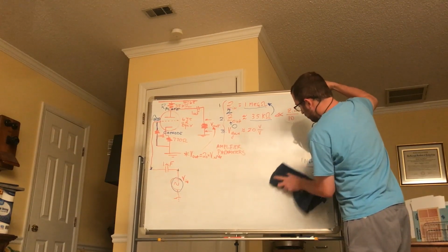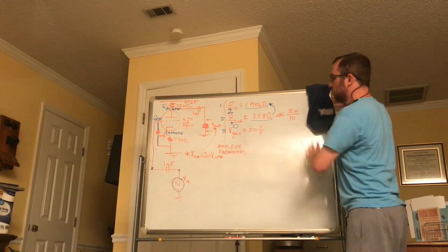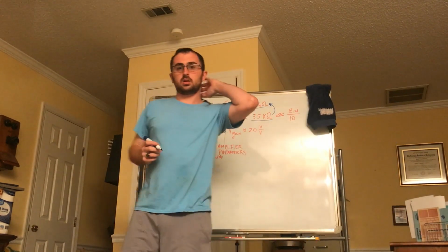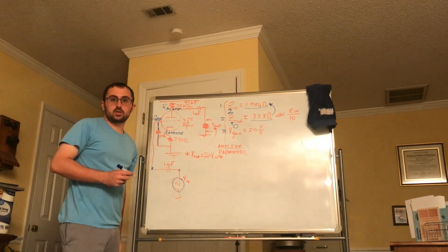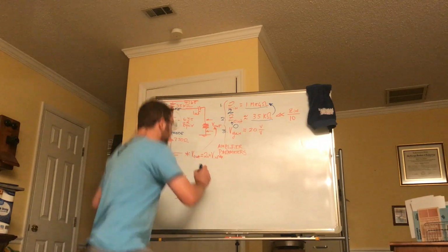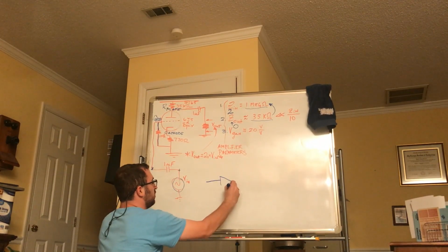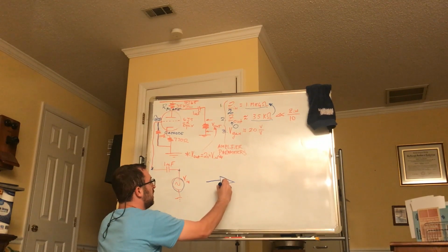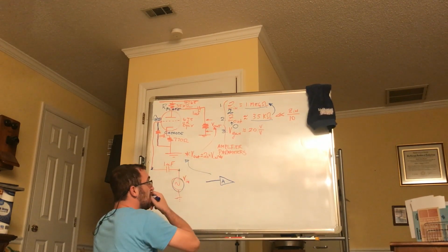Alright, so in practice, what you do with amplifiers is you can't really get a larger gain than so much. So what you do in practice is you cascade them. So in the amplifier I made, you have your first amplifier, we'll call it A, which is this circuit here.